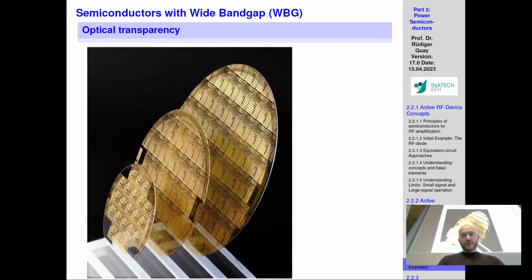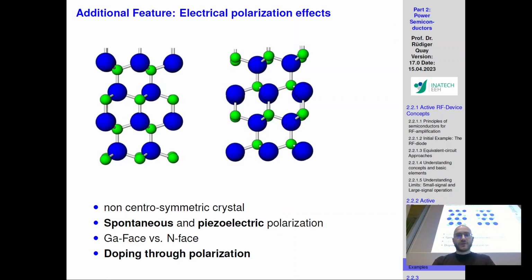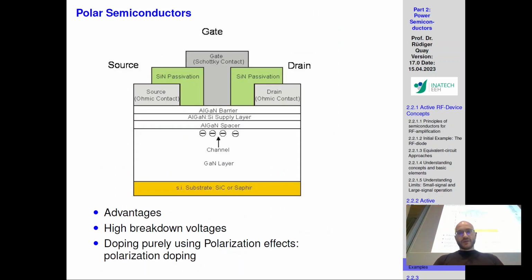Not only that, and some good-to-know facts: because of the band gap, they have the property of see-through substrates, but this is all just in how the spontaneous and piezoelectric polarization happens in between, and the creation of the 2-DEG layer. These are good things to know, and they're important for understanding how these devices function and operate, but won't be a significant addition to the exam. I think, what did we want to say? Yeah, this is also part of this.